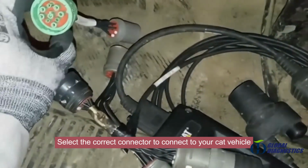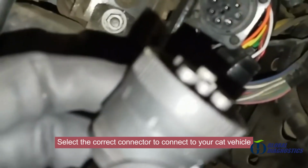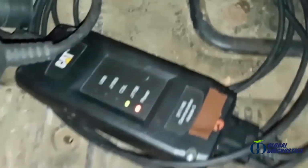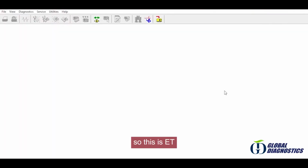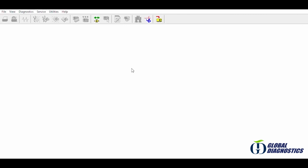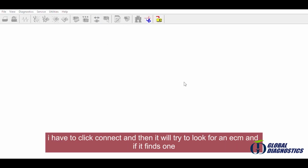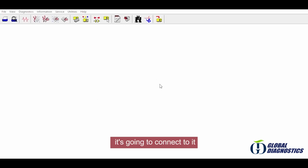Select the correct connector to connect to your Cat vehicle. So this is ET itself when you first connect or at least boot up the program. Mine is set to not automatically connect. I have to click connect and then it will try to look for an ECM, and if it finds one, it's going to connect to it.